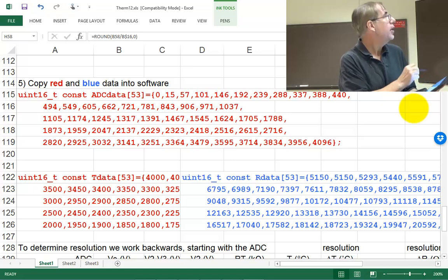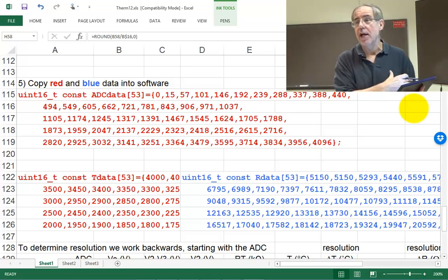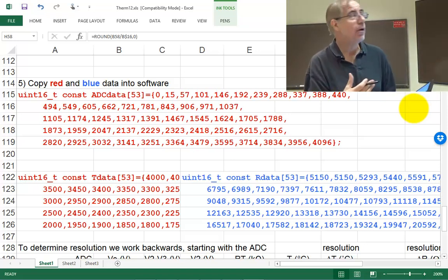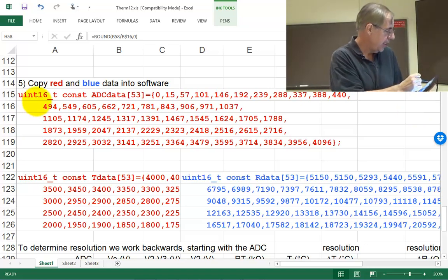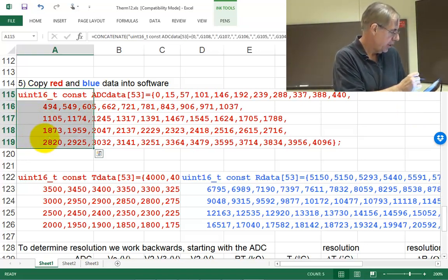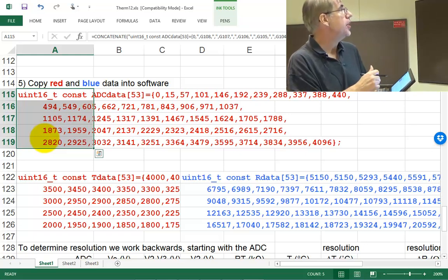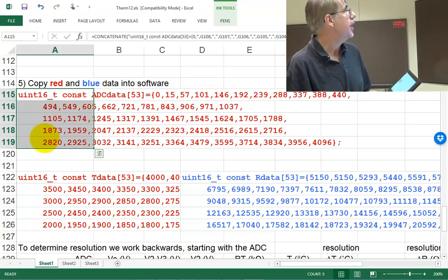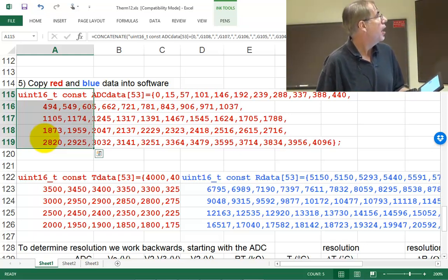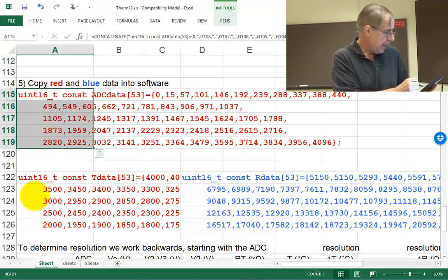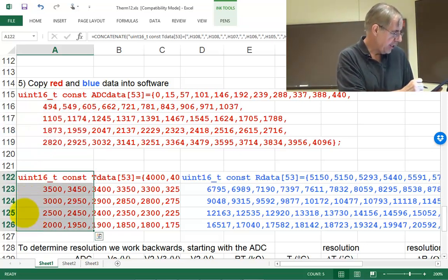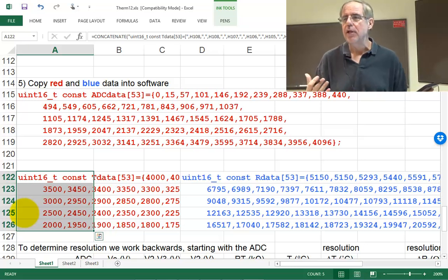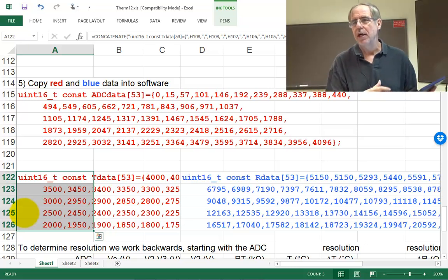It gives me two pieces of data structure that I can copy into my program. So I can take this guy here, copy that, which is a table of 53 data points, 51 in the middle and an extra point on the inside and the outside, and then the corresponding temperature data here. And so now I can use a table lookup with interpolation.